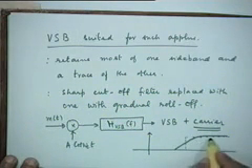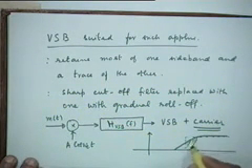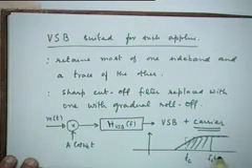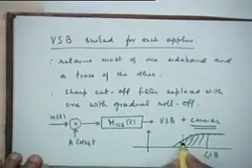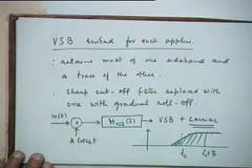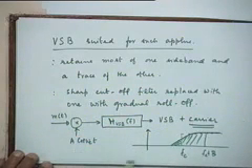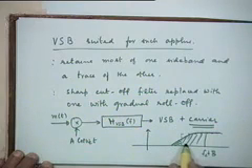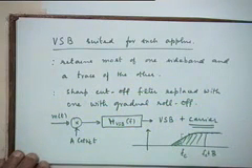So you will be transmitting most of the upper sideband. Let's say the bandwidth is B, right? So this is f sub C, this is f sub C plus B, but you are also transmitting this portion of the lower sideband. Right? It could be the other way around. You could be transmitting most of the lower sideband and a small portion of the upper sideband. It could be either way.